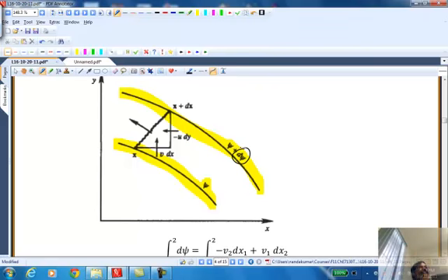Okay. Now, this delta psi is a direct measure of the flow rate. Okay, so any liquid that gets in through this cannot, by definition, cross. Can a velocity vector be like this? Because we just said that it has to be always tangential. So there cannot be a cross flow. The flow cannot cross a streamline. Okay? And so whatever fluid that enters here must leave there.